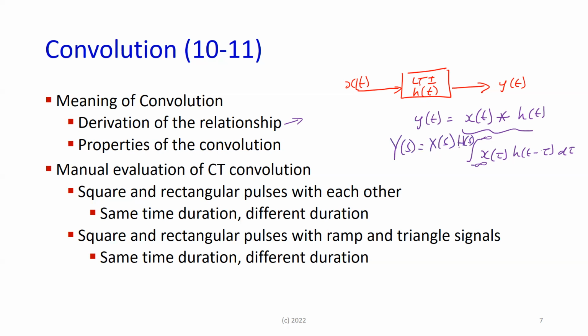But what if X(s) wasn't easy to come by? For instance, a simple thing like a rectangular pulse, a start and a stop: defining that in terms of the Laplace transform, you have a step, you have another step that is a negative going step, and the difference between the two of them.